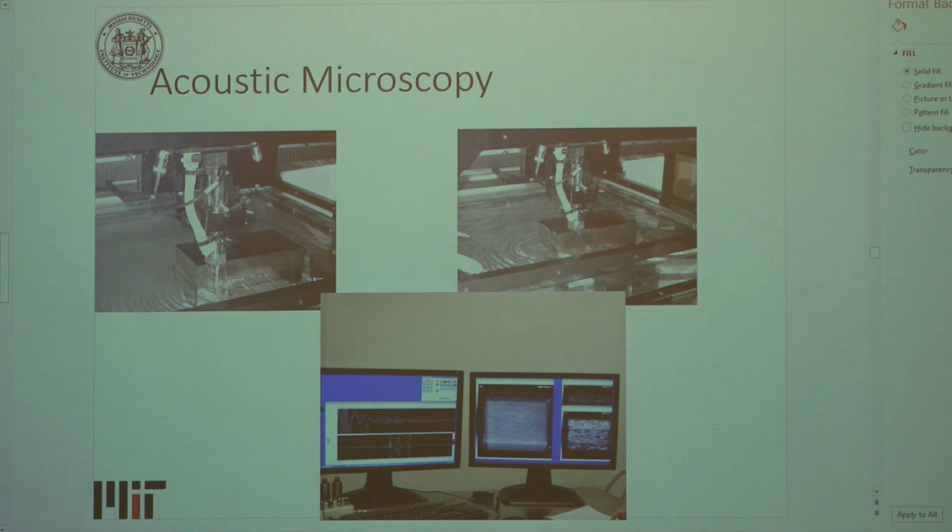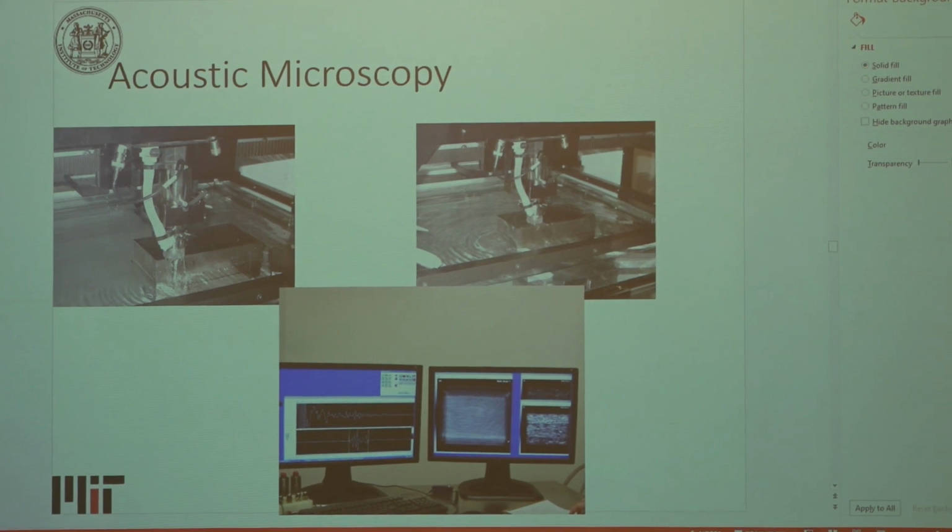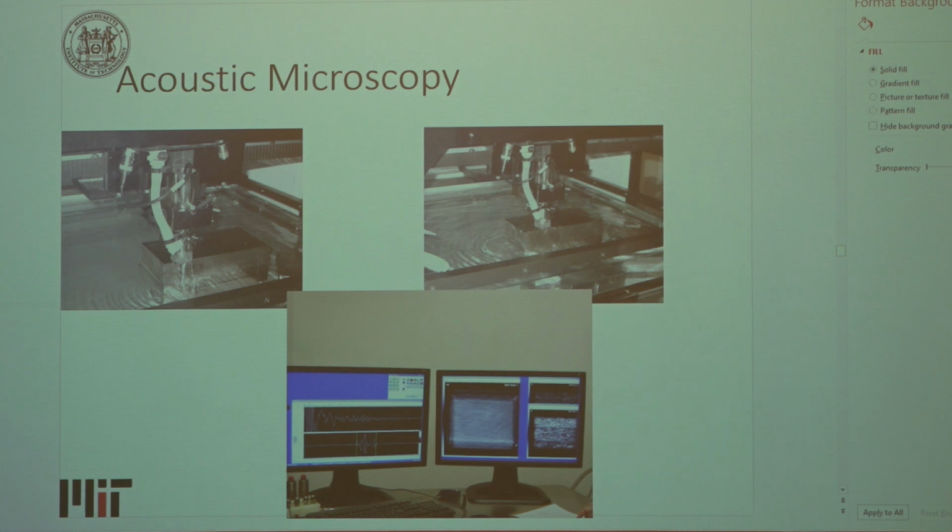But what you're seeing in the image here that I wanted to point out was there's quite a bit of noise in the output. So there is a trade-off between the noise that you can accept in the output versus if you just want to see if there's a flaw or no flaw. That's the hit-miss data versus A hat. There's two different ways to do the statistics to get that 90/95 value. Depending on which one you choose, you can either do a whole bunch of experiments or you can do fewer experiments with more opportunities on each sample.